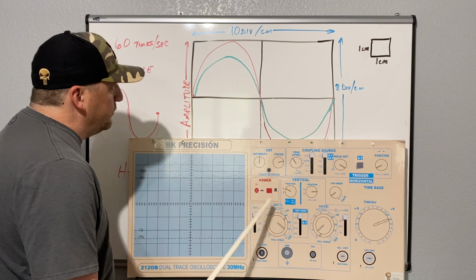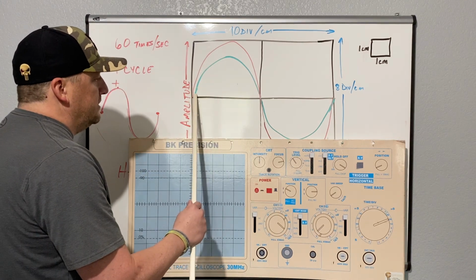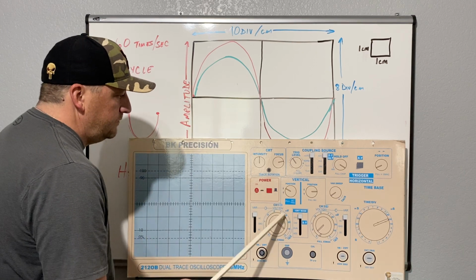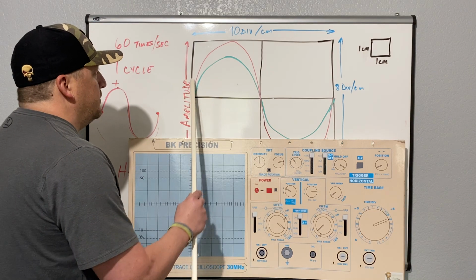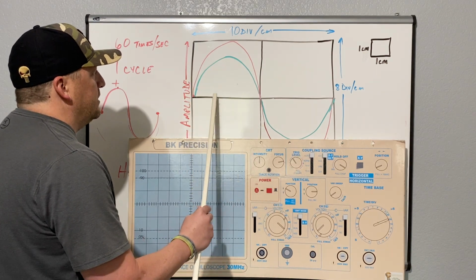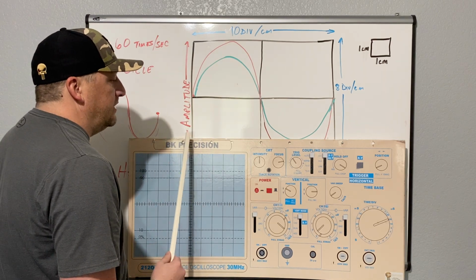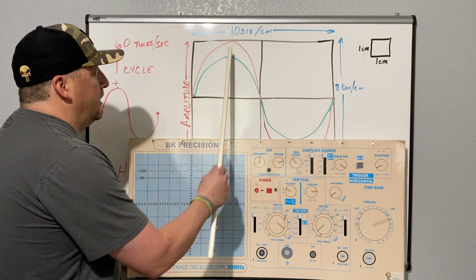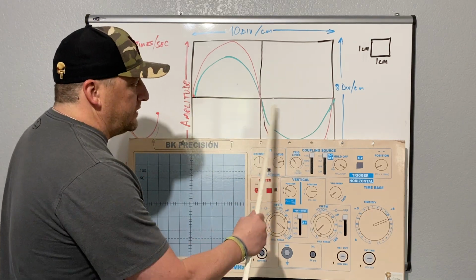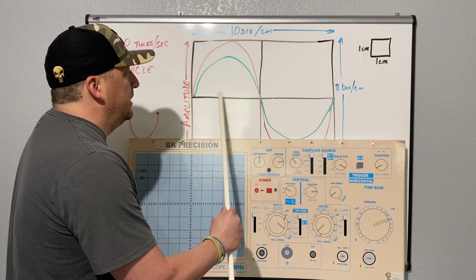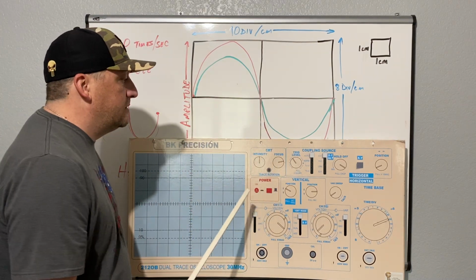You get into that millivolt range. So if this is set to a 50 millivolt scale, and we've got this signal that we're looking at here, this is a positive going signal of 200 millivolts. This is a negative going signal on this other side that we drew, the red one, of 200 millivolts.